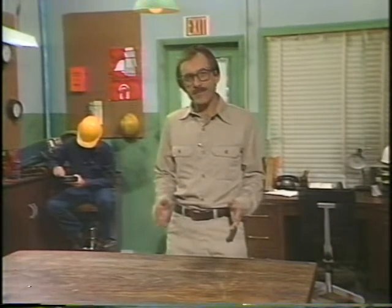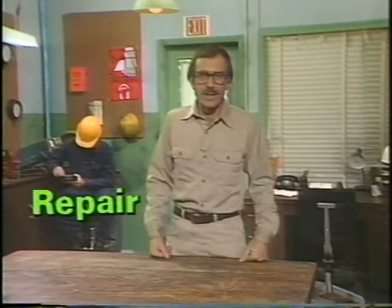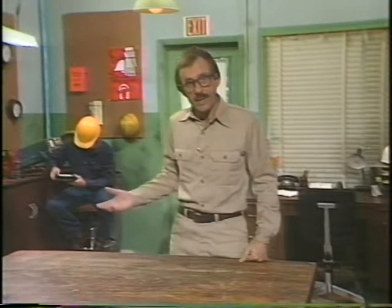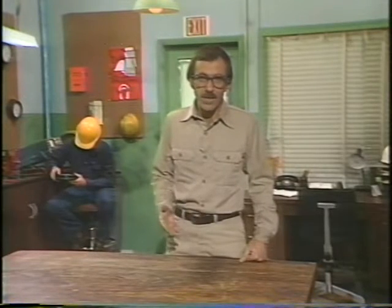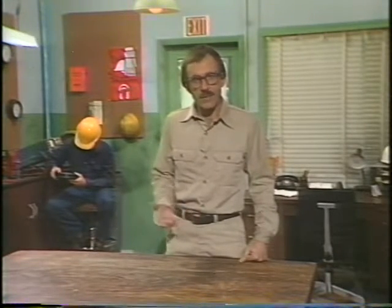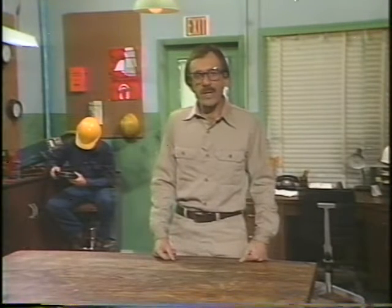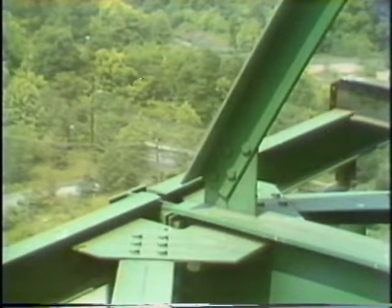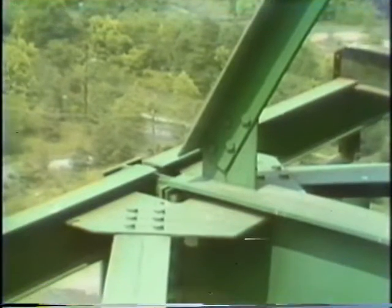What you've got to do next is repair the problem. The repair work can be done either right there where the instrument's located or back in the instrument shop. It depends on the type of repair that's got to be done. More complicated repairs often have to be done in the shop. Sometimes the environment the work's got to be done in is another factor. For repairs that have to be done under unfavorable conditions, it's usually more efficient and safer to do the work in the shop. If you're not sure where the instrument should be repaired, check the instrument service manual.